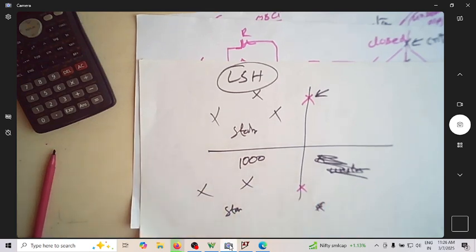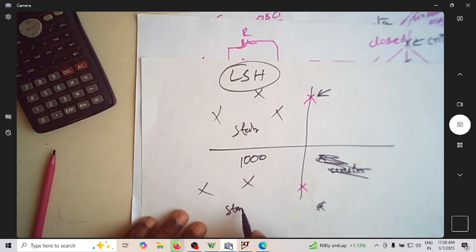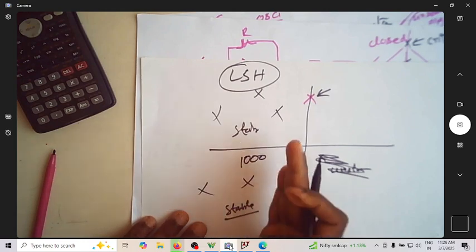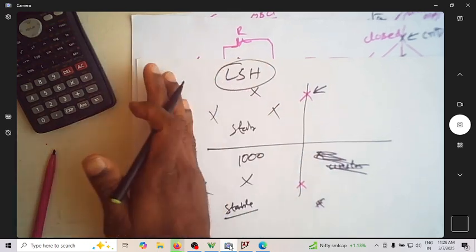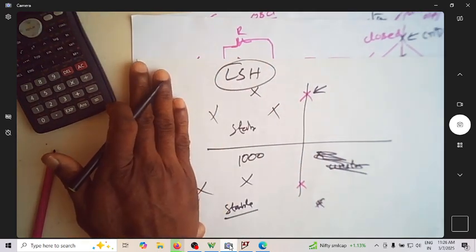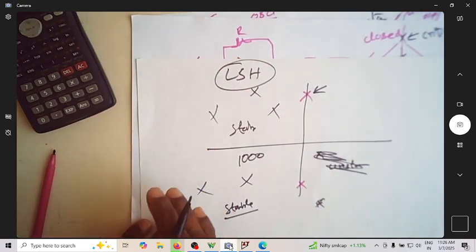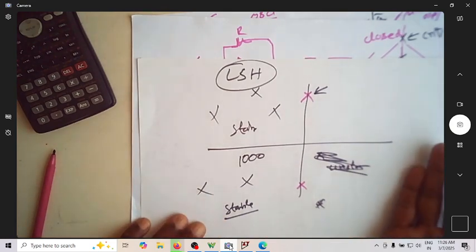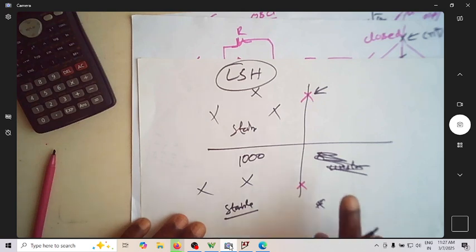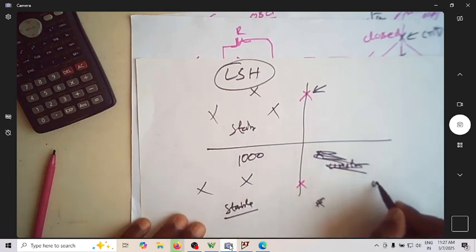So what is the whole story? The whole story is, for a system to be stable, all closed loop poles should be on the left hand side. Even if a single closed loop pole goes to the right hand side of the S-plane, the system is unstable.